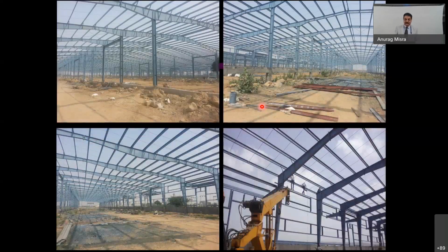Then you have large span structures. This is one of the warehouse buildings where you could see that this building is about 200-meter long and 75-meter wide. So depending on the requirements, some intermediate supports were created. And you can see that the structural components are made in pieces. There is one joint here, another one is here. And depths also are varying because these are the points of contraflexure. And the same you can see here, that is the connection to the column.